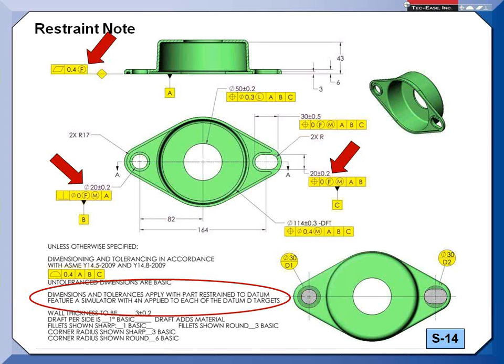That illustration that you have, those arrows where you have the free state before the modifier and the tolerance portion, is that specific to the molded standard? Because that's in conflict with the 14.5. Uh-oh. Are the free states supposed to go after the M's? After the modifiers, that's what the standard says. The 14.5 says. Oh. So we're following the modifiers.